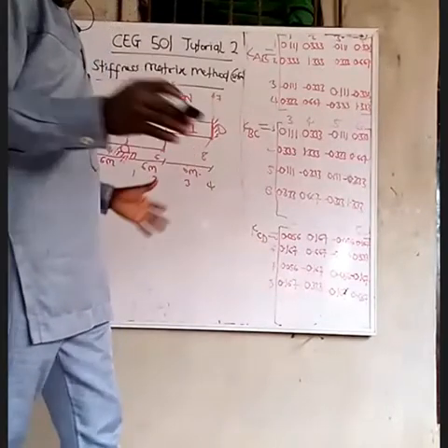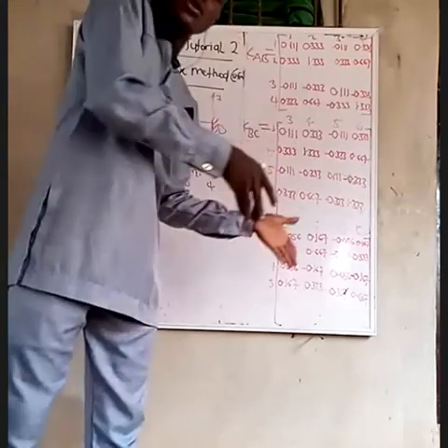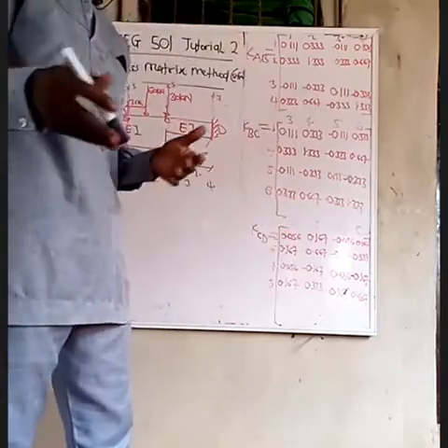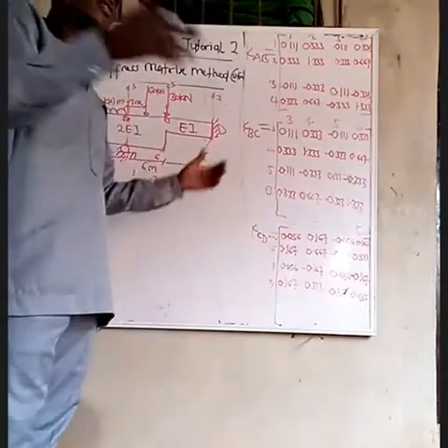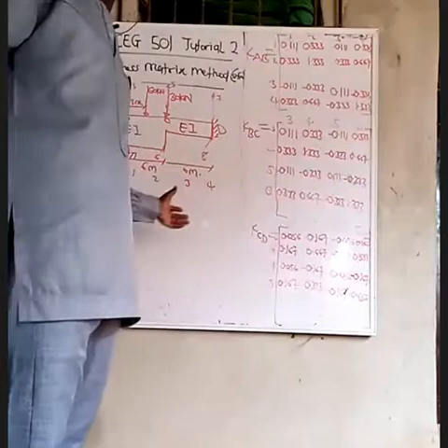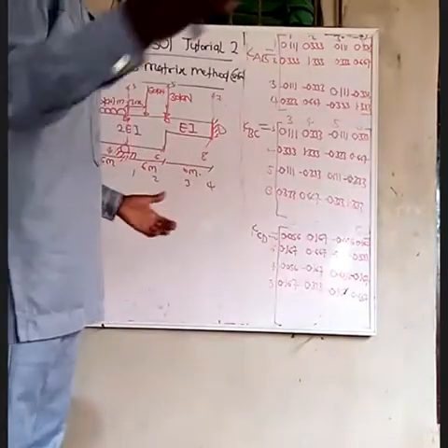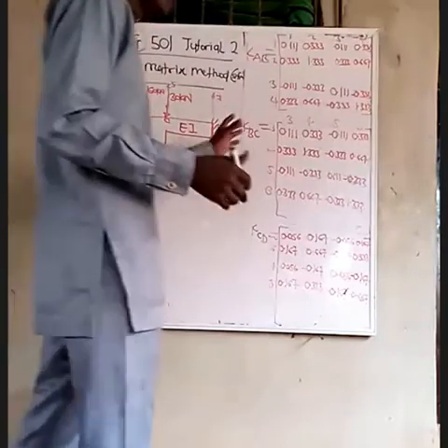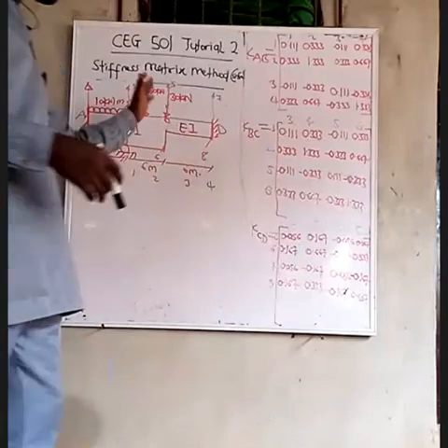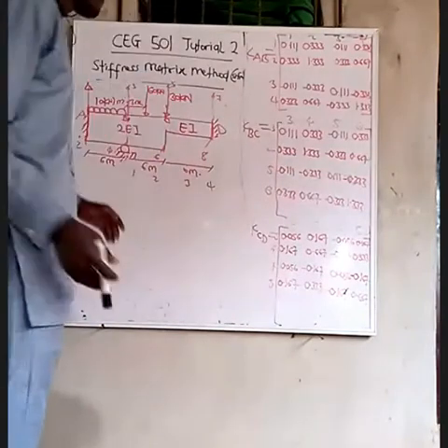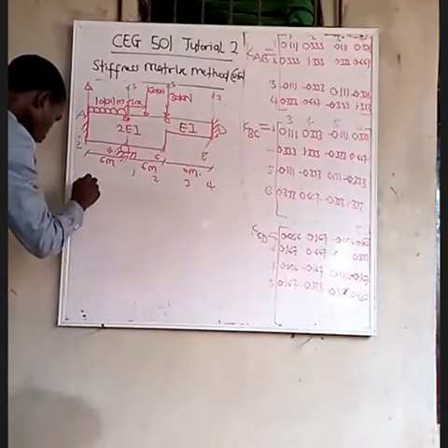That would be very stressful for you. So what we used to do, in order to get what we need very fast, is simply bring those unknown displacements close to the front, so that you obtain just 3 columns, 8 rows, instead of obtaining 8 rows, 8 columns and using only 3 parts of it. So you bring those unknowns that you want to calculate, D5, D4, to the front.